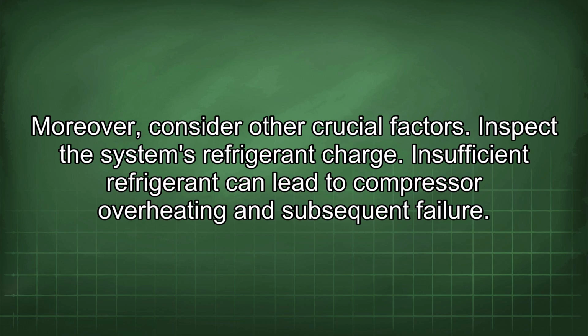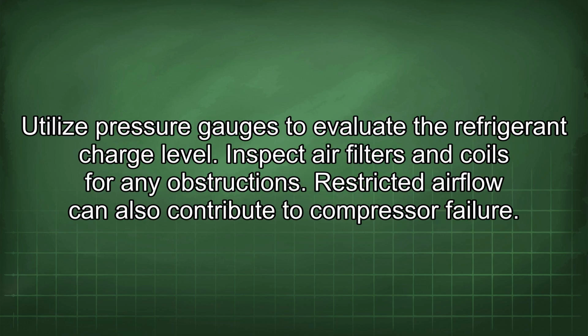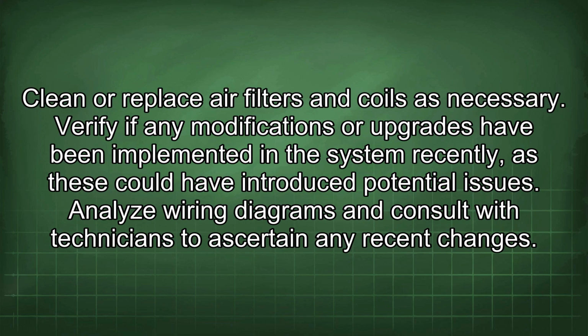Inspect the system's refrigerant charge. Insufficient refrigerant can lead to compressor overheating and subsequent failure. Utilize pressure gauges to evaluate the refrigerant charge level. Inspect air filters and coils for any obstructions. Restricted airflow can also contribute to compressor failure. Clean or replace air filters and coils as necessary.